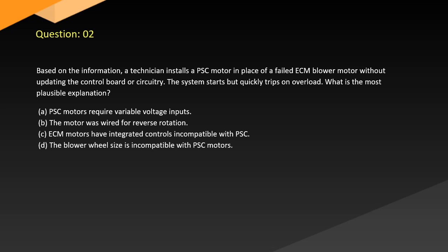A. PSC motors require variable voltage inputs. B. The motor was wired for reverse rotation. C. The ECM motors have integrated controls incompatible with PSC. D. The blower wheel size is incompatible with PSC motors.